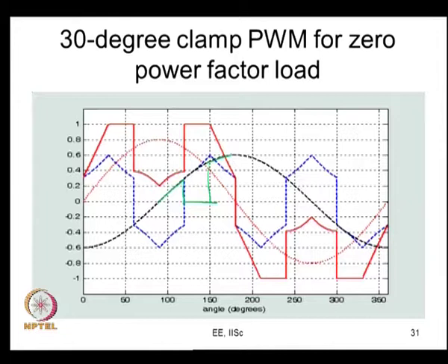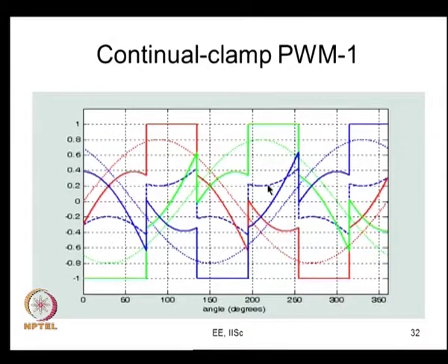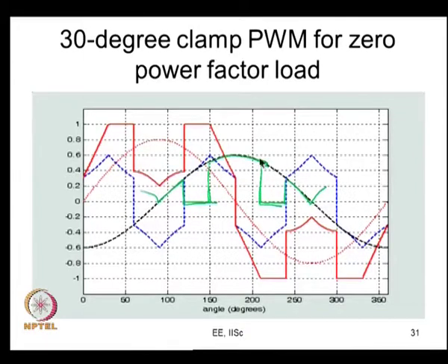then here it goes. This is one half cycle of the energy loss. So, you see that it starts increasing on this side again. From here to here, you cannot clamp close to the peak. So, you are clamping between, if you call this 0, 30 to 60 degrees and 120 to 150 degrees. Ideally you want to clamp between 60 to 120, but it is not possible at all. So, you are doing this now.